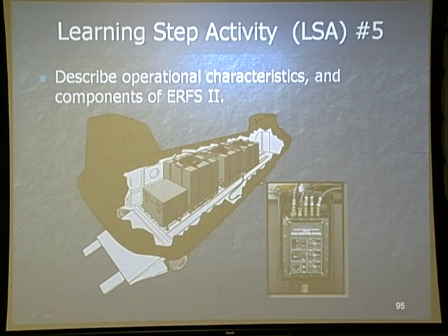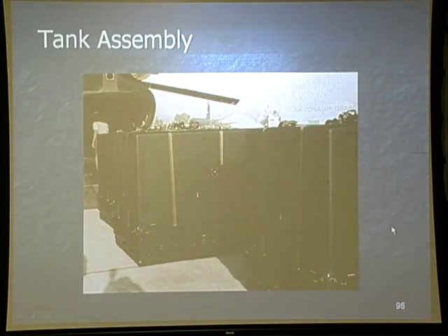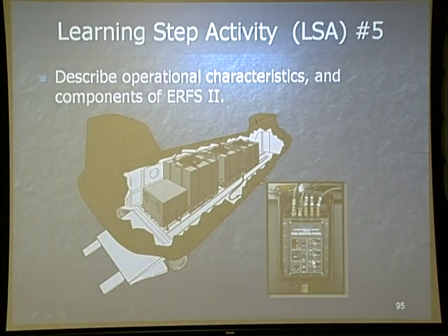Here's the first tank and your control panel for actually monitoring and controlling the pumps to the system. All operated via the crew member, and you have your fuel quantity indicator that will only tell you how much fuel you have in the IRFs. And it has a selector for which IRFs you're looking at. And you can manually control either pump, controlling and dictating what the order is of pumping fuel.